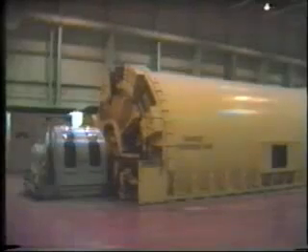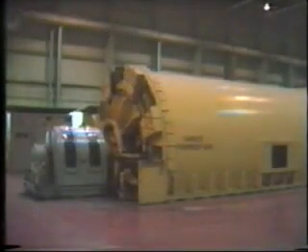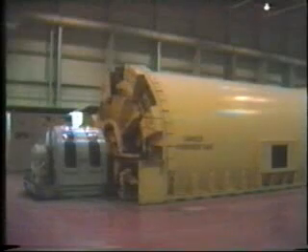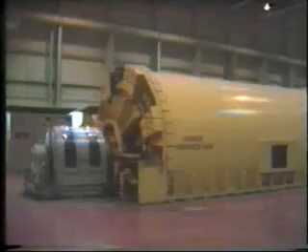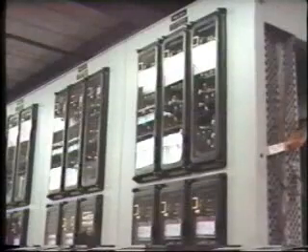In practice, it is probable that the generator automatic controls may attempt to increase generator internal voltage in order to compensate for some of the voltage drop downstream. However, this would take some seconds and therefore should not interfere with the operation of protection relays, nor with our studies of fault characteristics. Let's take our study a step further now and consider the magnitude and phase angle of